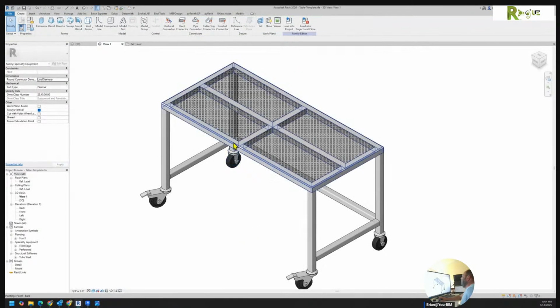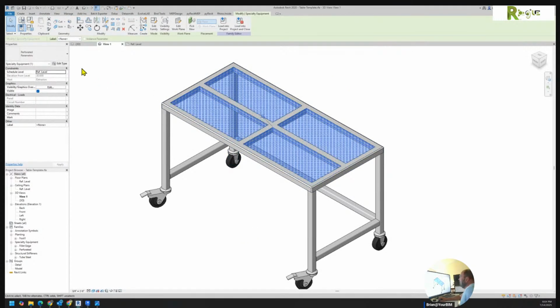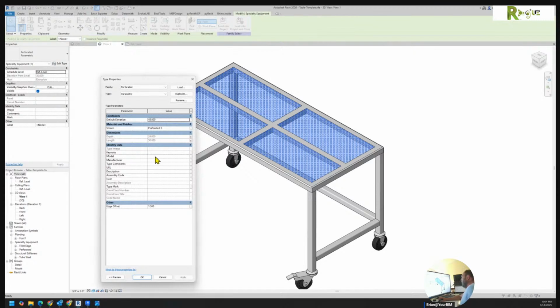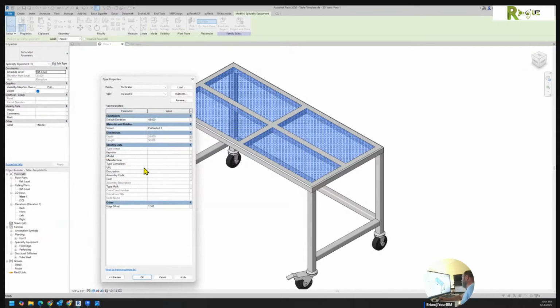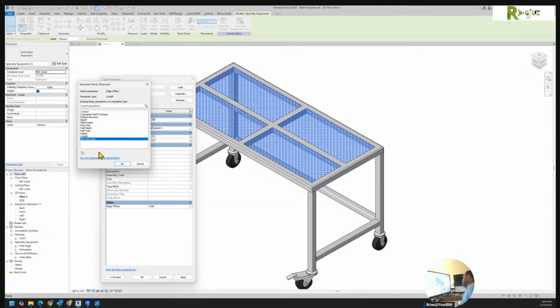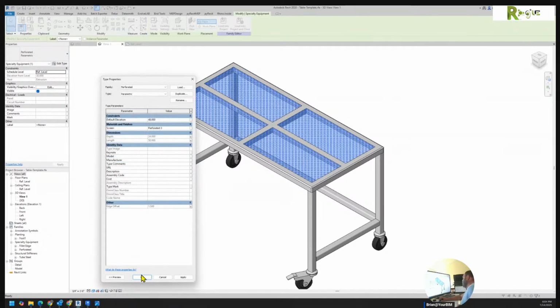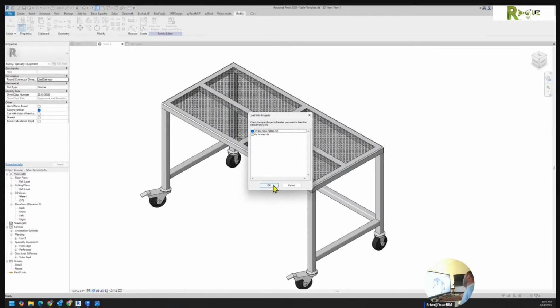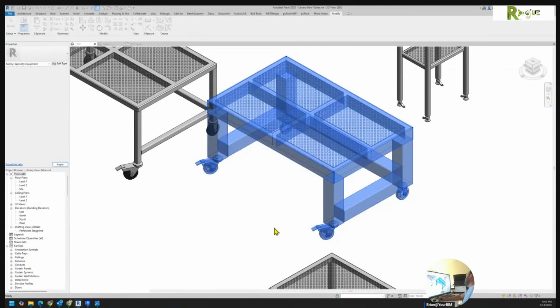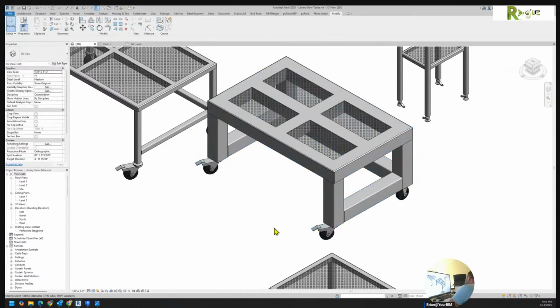Well, if I go into that family, what you're going to find is this subfamily. I have the depth and the length equaling something in the project, equaling the depth and the length. But you see my edge offset? I didn't have it match the structure size. Had it matched the structure size, what we would end up seeing is that everything in that thing should have remained 4 inches. Okay? That's pretty beneficial if you think about the level of impact there.